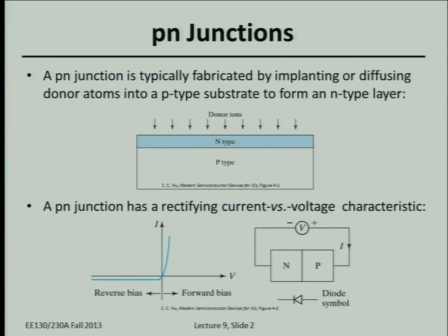So I just wanted to mention, in an integrated circuit, we have a lot of transistors, and the transistors have heavily doped regions to form, let's say, the source and drain electrodes of a transistor. And the way that we form that is illustrated here in this slide. So we start with a wafer that's usually moderately or lightly doped. So let's say it's doped p-type. Then we form the source and drain regions by implanting, just basically shooting in, like sandblast. It's not sandblasting. It's like shooting in with a shotgun,